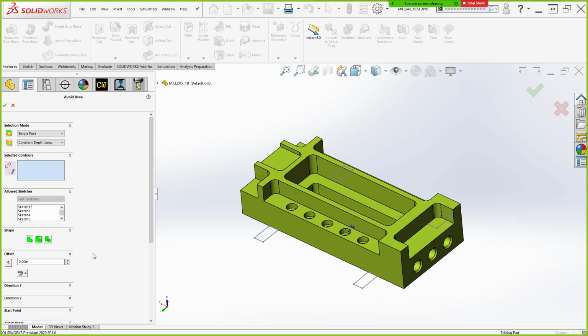sketches in. Well, over in the property manager here, you have a couple options for shape. So we have silhouette, we have a bounding box, right? So that kind of creates an XY bounding box around an irregular shape. And then the last option we have here is multiple.